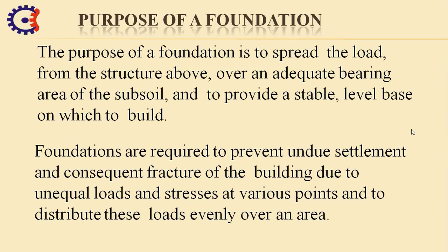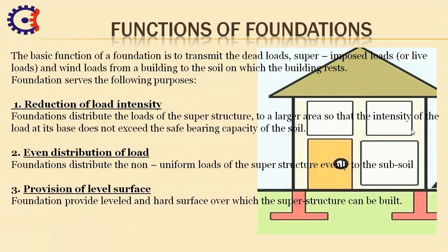So basically the purpose of foundation is to spread the load from the structure above over an adequate bearing area of subsoil and provide a stable level base on which to build. Foundations are required to prevent undue settlement and consequent fracture of the building due to unequal loads and stresses at various points, and to distribute these loads evenly over an area.